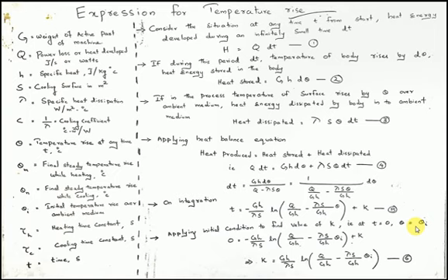See, there are actually two starting conditions for a machine. One is cold start. Cold start is the condition which I have just mentioned now. In cold start, you are starting the machine for the very first time in a day. So at that particular instant when you are about to start the machine, the surface of the machine will have the same temperature as that of the ambient medium. So there will not be any temperature rise theta I. The value of theta I will be 0.